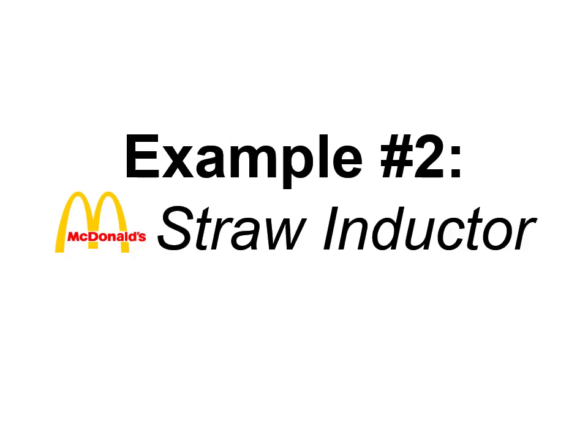This is a fun example. A lot of times when we're having fun in the lab, we'll need an inductor that has a certain value. Maybe it's going into a power supply or a filter or something else. It turns out we can wind magnet wire around a McDonald's straw and actually get an inductor that has a pretty accurate value of inductance. And we can use our analysis of a solenoid to come up with an easy design rule that will let us do this.